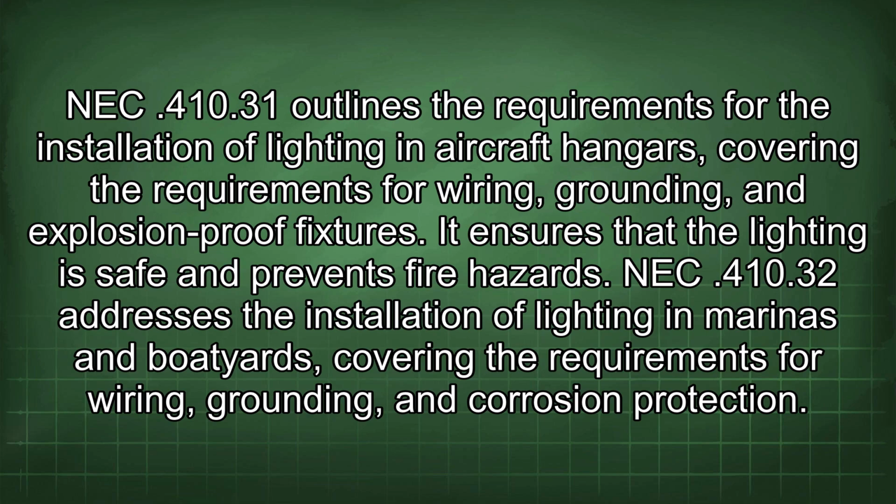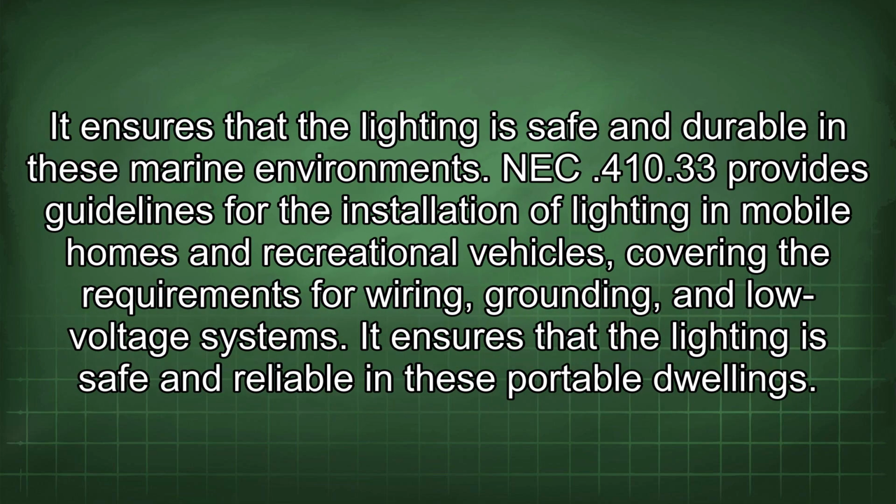NEC 410.31 outlines the requirements for the installation of lighting in aircraft hangars, covering the requirements for wiring, grounding, and explosion-proof fixtures. It ensures that the lighting is safe and prevents fire hazards. NEC 410.32 addresses the installation of lighting in marinas and boatyards, covering the requirements for wiring, grounding, and corrosion protection. It ensures that the lighting is safe and durable in these marine environments.